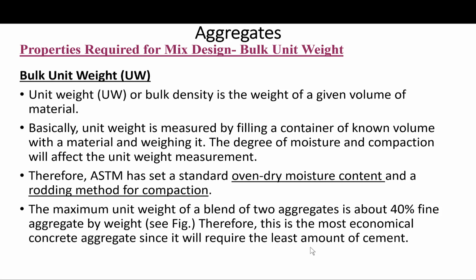Basically, we're talking about the voids being less, so you require less cement paste. But again, I will keep mentioning, we have a compromise between workability, economy, and of course, strength. I'm not worried too much about strength, because we can achieve it. I'm worried about durability and workability, basically. Durability for long-term performance, workability for handling.